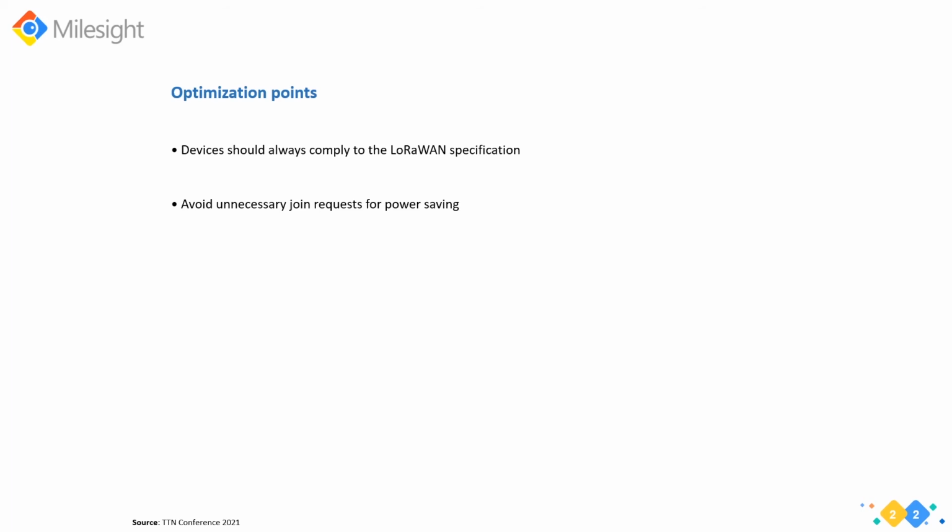Or maybe you can be smart with your data. You could, for example, transmit every 5 minutes, or you could only transmit when your sensor value changes by more than a certain threshold.